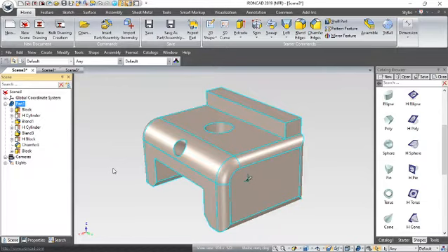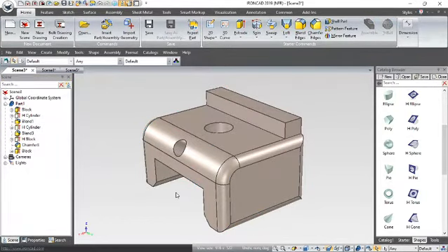If you did that in a traditional system where you're reliant so much on work planes and sketches and everything else, then that becomes quite a time-consuming business. Especially with things like circles on a curve, you'd have to put a work plane on there at a specific angle, then create a circle and extrude that with a cut down through the part. So it's a very powerful tool. Hope that's given you some idea of the basics of using IronCAD.